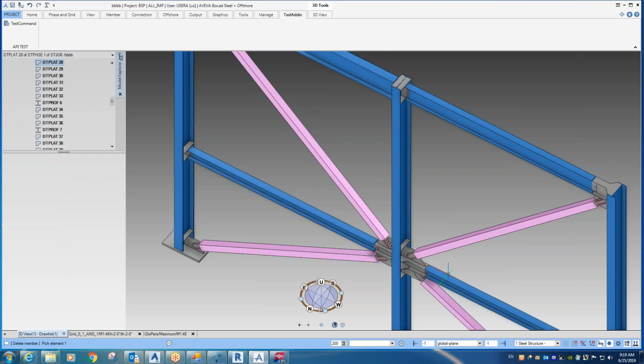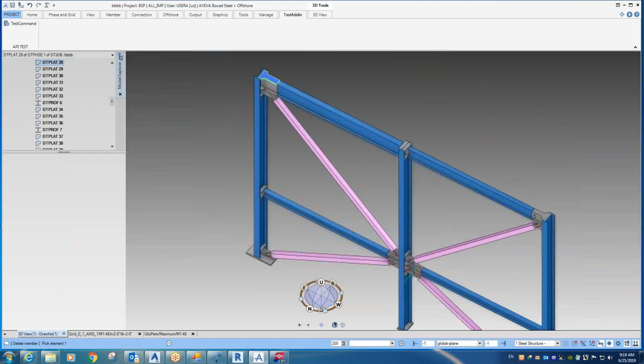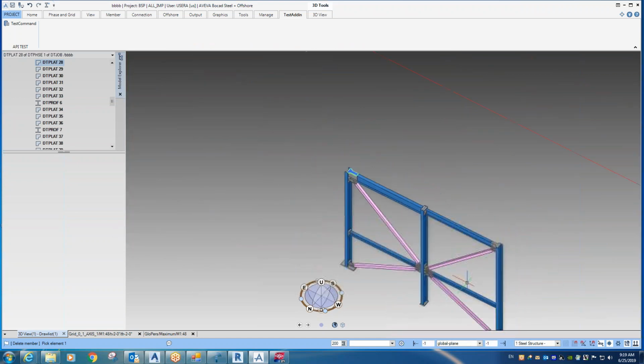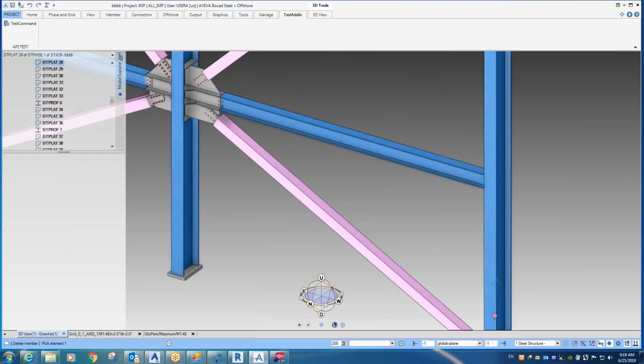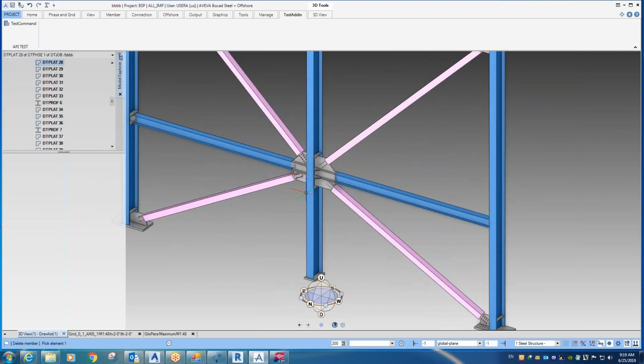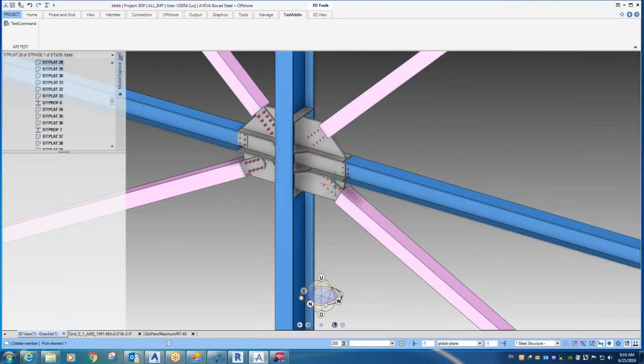We're ingesting the input file that the connection builder generates, and using the Bocad APIs, we're building this model with connections. Okay. So its ability to call what is it, Luke? The plates, the beams, the plates, the bolts, the cuts. We're using all those APIs to generate this model.